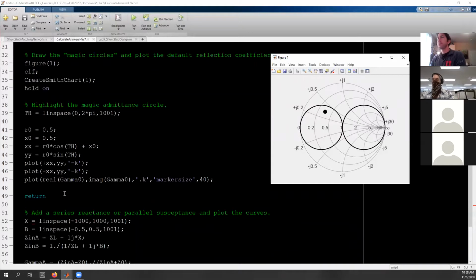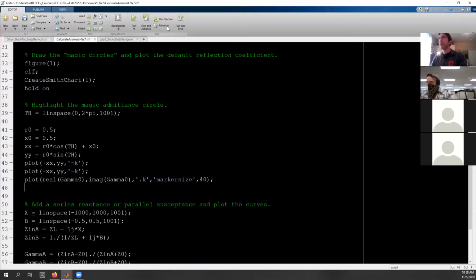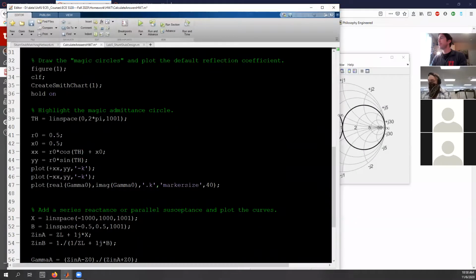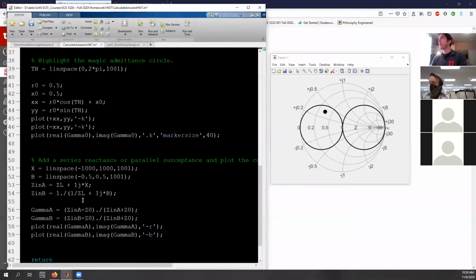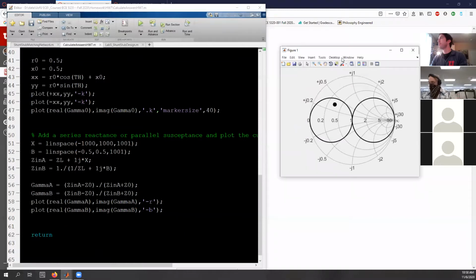That was my fault. So sorry to keep coming back to this, but Pozar specifically states, if normalized impedance is inside of your resistance magic circle, thou shalt use a high-low network. We're doing a low-high network. So we're doing in contradiction of the text. No, inside he's saying inside this circle, you must do a high-low. Yes. If the normalized impedance ZL divided by Z naught is inside the 1 plus jX circle on the Smith chart, then figure 5.2a should be used, and that is what we have defined as the high-low.